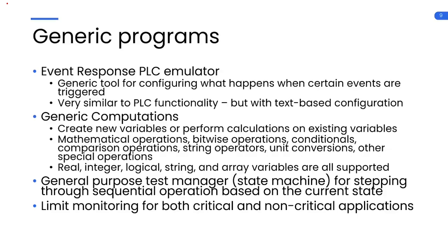So in one mode you're going to turn on the drive and enable it. In the next mode you're going to check that the bus voltage increased, and then in the next mode you might reset the faults. Mode after that you might check that the faults were reset successfully, and then you can go to this state if they weren't and that state if they were.